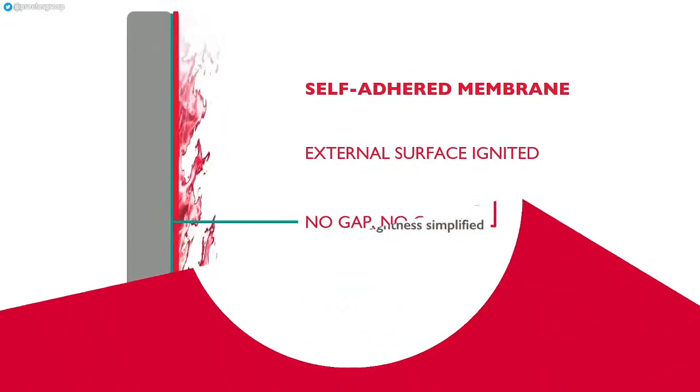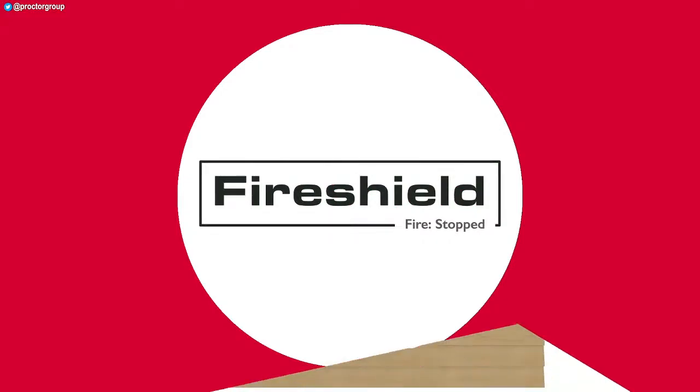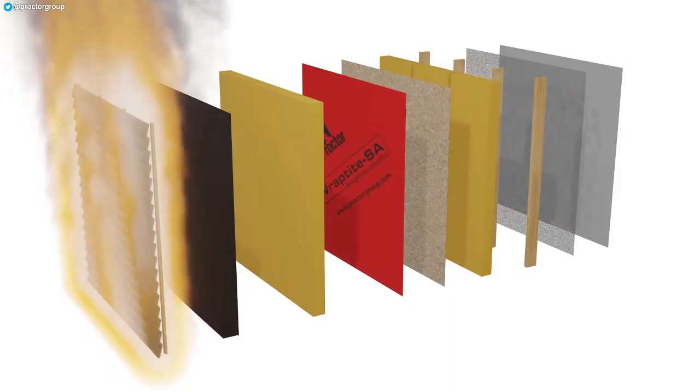So, we've looked at how the Raptite membrane reacts to fire and how it complies with the relevant technical standards. But if we want to go beyond fire resistance and introduce a degree of fire protection, then another option is to use the Fire Shield membrane. Fire Shield is a vapor-permeable membrane with a unique surface composition which actively reacts to prevent fire taking hold. Fire Shield can be used over insulation boards to provide an additional layer of fire protection to the internal structure of the building, or can be used directly onto the sheathing boards of a timber frame structure.